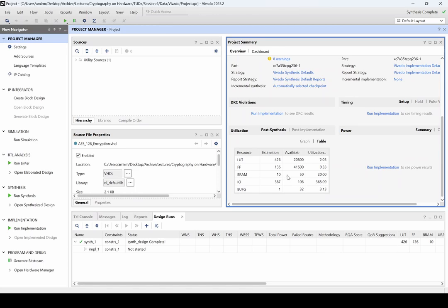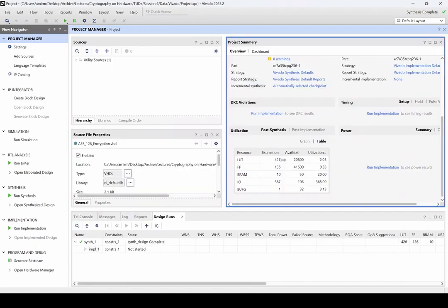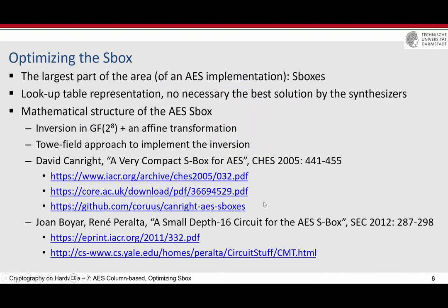But then again, we discussed this: the block RAM implementations are dedicated to FPGAs, and you cannot compare one design which doesn't use block RAM with another design which does. In some implementations you have the opportunity to use block RAMs, and in others not at all, for example when it is not an FPGA implementation. If you examine this, you have to compare them in a fair way. It means that the same FPGA should be used.